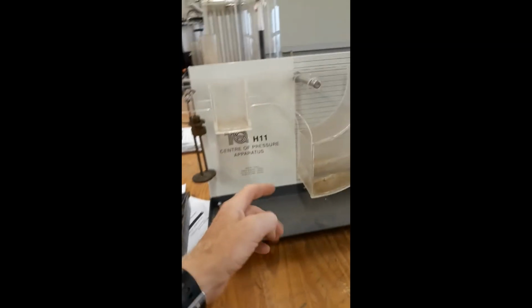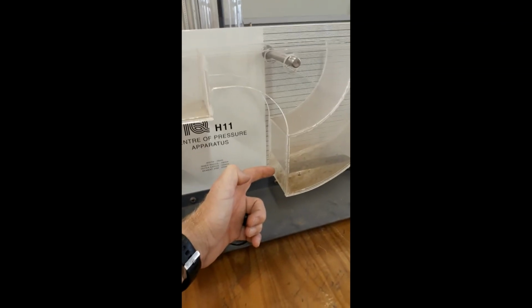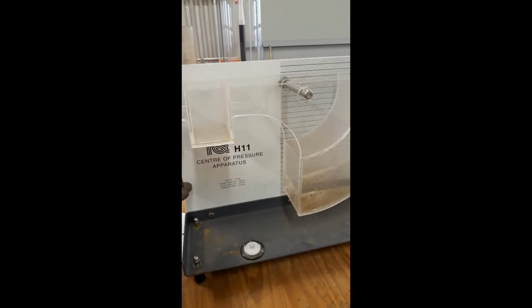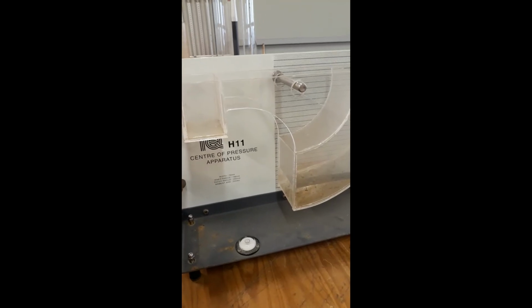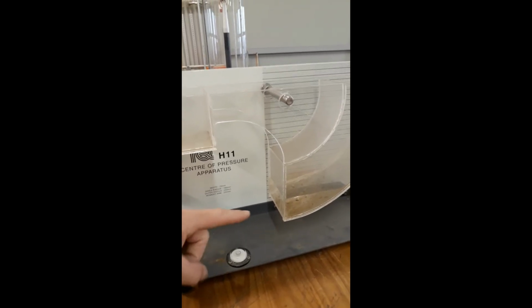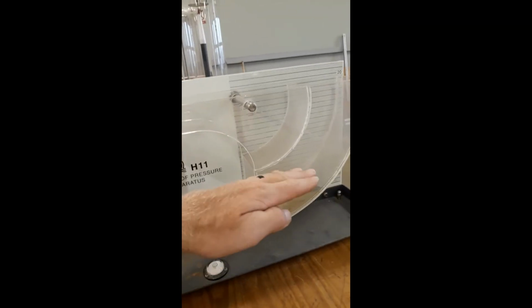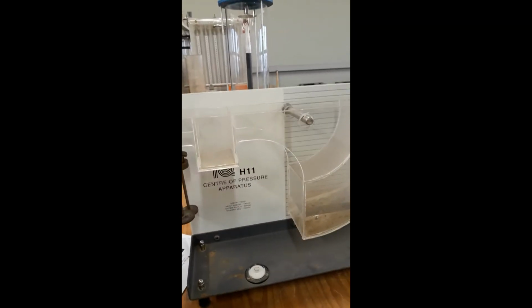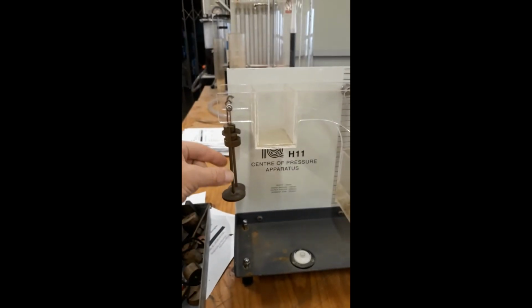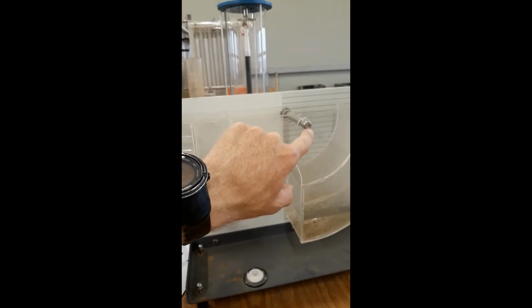Now the force acting on this plane at the COP equals the moment caused by this weight. The force on that plane around the pivot point creates a moment which is equal to the moment caused by the weight around that pivot point.